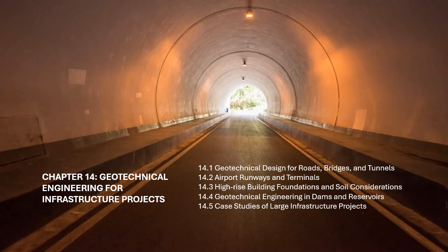The interaction between the bridge piles and the surrounding soil affects the distribution of stresses in the foundation and the overall performance of the bridge. Seismic considerations. In areas prone to seismic activity, the geotechnical design must account for potential ground shaking, soil liquefaction, and other earthquake-induced effects. Engineers use dynamic soil structure interaction analyses to assess the bridge's response to seismic events and ensure that the structure can withstand the forces generated during an earthquake.